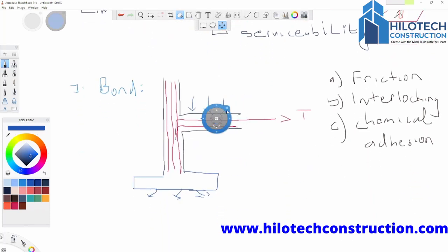If the length that you give for this rod is not accurate, you are going to discover that the load, because if it is long, it is going to transfer it here, but if it is not long, the load will be carried by the beam itself. And when the load is carried by the beam and not transferred accurately to the pillar, cracks might develop at the beam here, or in the worst case scenario, it can lead to a total collapse of this structure.